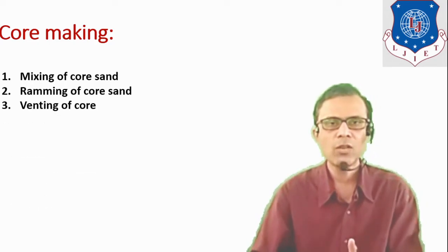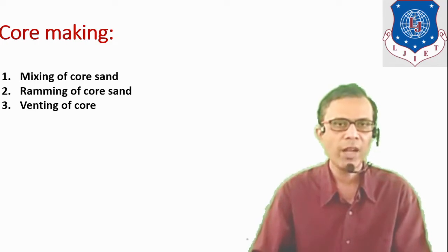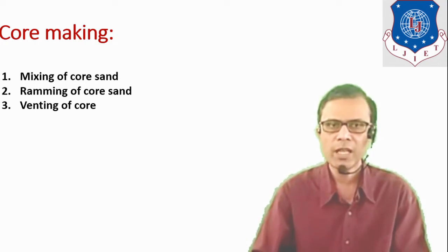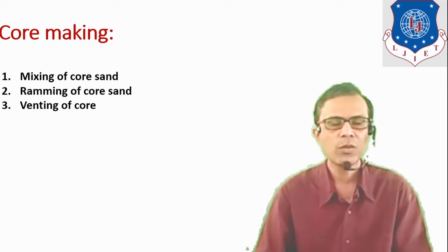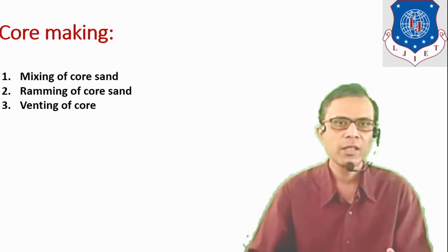Then venting of the core. To remove the entrapped gases, venting is done. It can be done with small diameter wires, and it will be helpful to let the gases escape which can otherwise be entrapped inside the core.